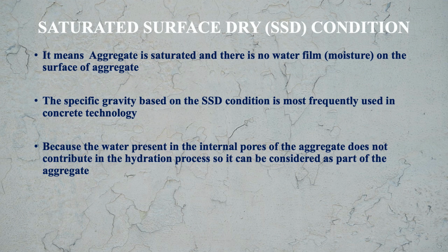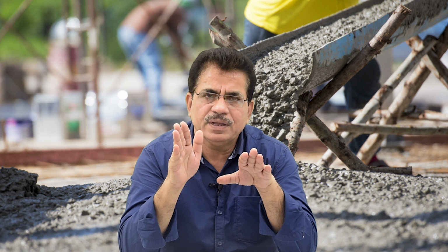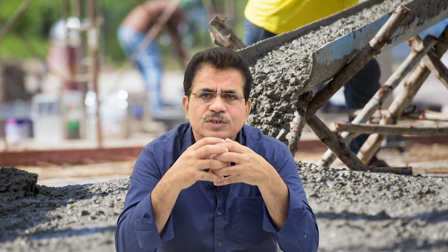The specific gravity based on the SSD condition is most frequently used in concrete technology. Because the water present in the internal pores of the aggregate does not contribute in the hydration process, so it can be considered as part of the aggregate basically. Means internal water present in the internal pores of the aggregate, we can just consider that water as the part of the aggregate. Now let us see water absorption of the aggregates.